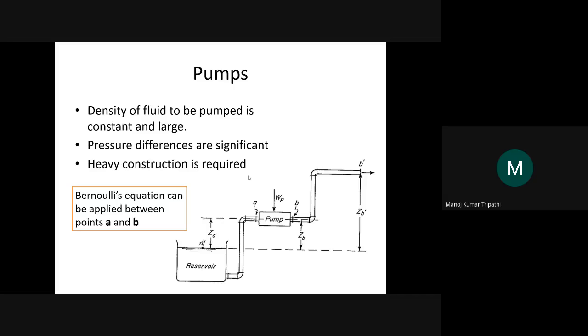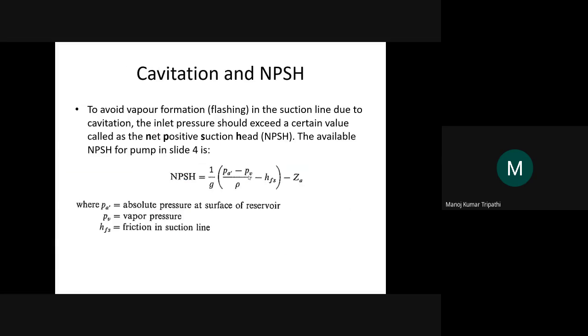And when they implode, they cause damage to the pump and the line also. And there are heavy oscillations in the pipe, in the flow, which can damage the pump, damage the line, and reduce the efficiency of the pump as well. So we don't want that to happen. Therefore, we want to keep a net positive suction head. That's the concept behind it. And you can read more about it in the PDF that I shared.